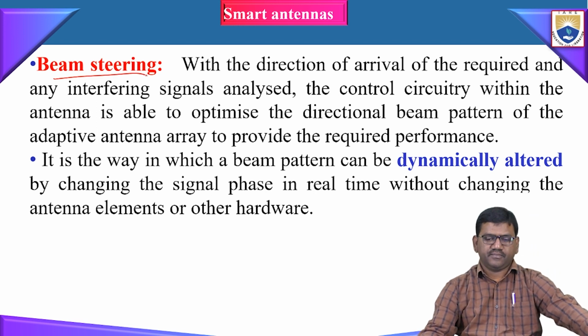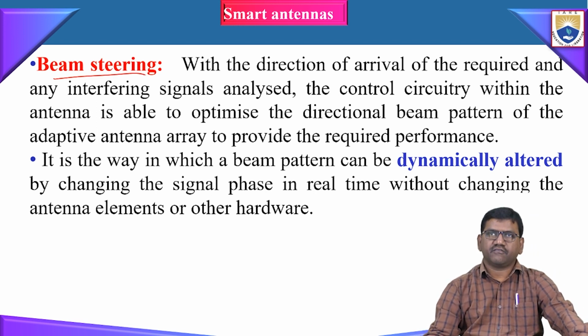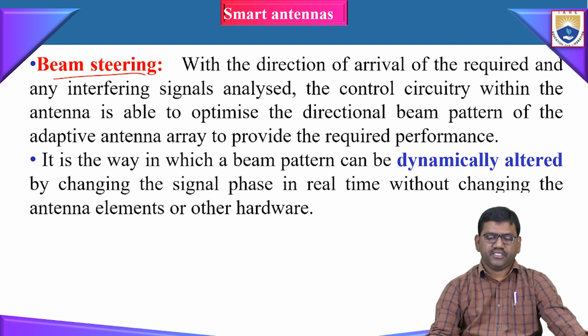The next definition is beam steering. So what is beam steering? With the direction of arrival of the required and interfering signals analyzed, the control circuitry within the antenna is able to optimize the directional beam pattern of the adaptive antenna array to provide the required performance. It is the method where the beam pattern can be dynamically altered by changing the signal phase in real time without changing the antenna elements or other hardware.